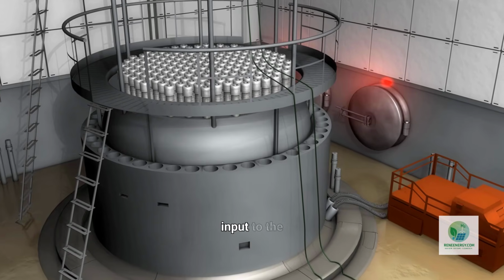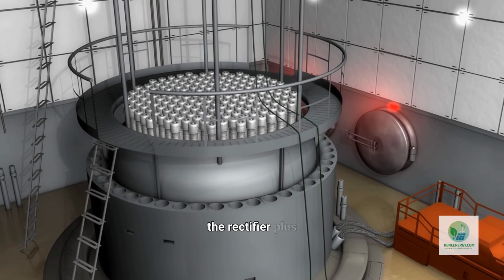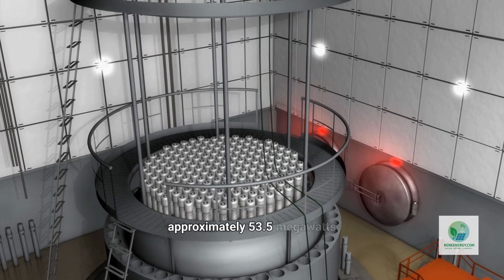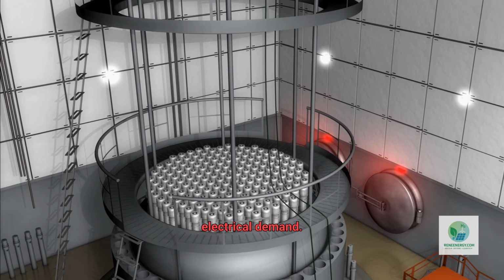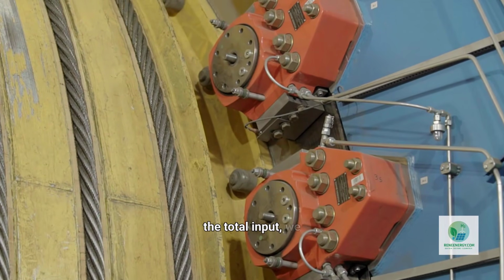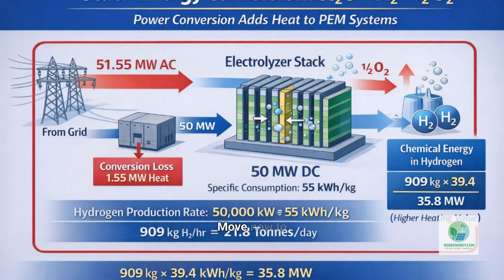Therefore, total AC input to the facility becomes 51.55 megawatts required at the rectifier, plus 2 megawatts for auxiliaries, resulting in approximately 53.5 megawatts of total plant electrical demand. This is the true plant level input. Now that we have established the total input, we can examine the energy conversion inside the stack. Move now to image number 4.